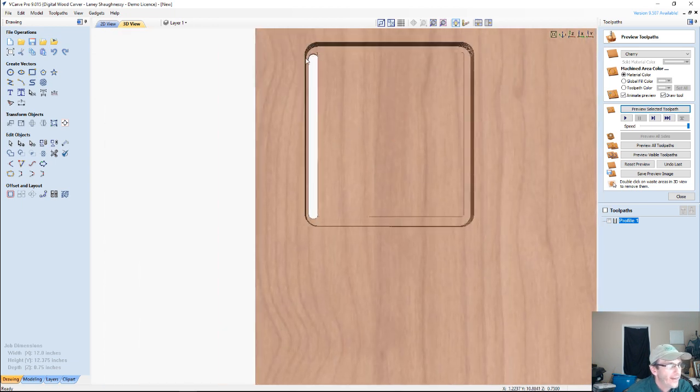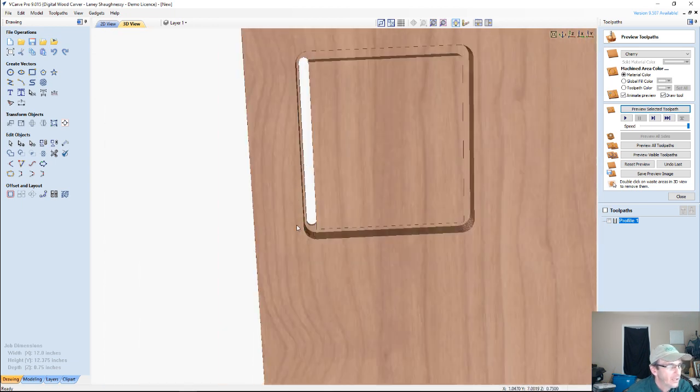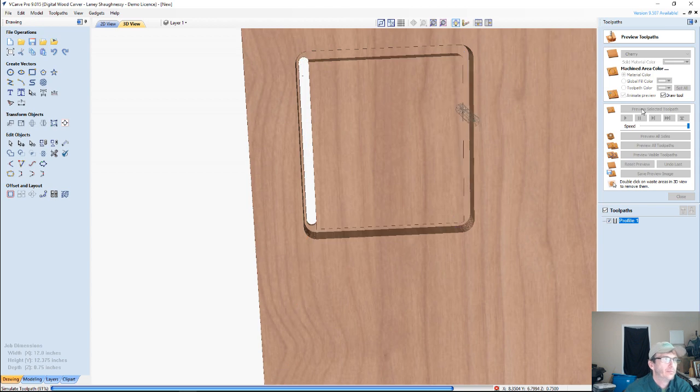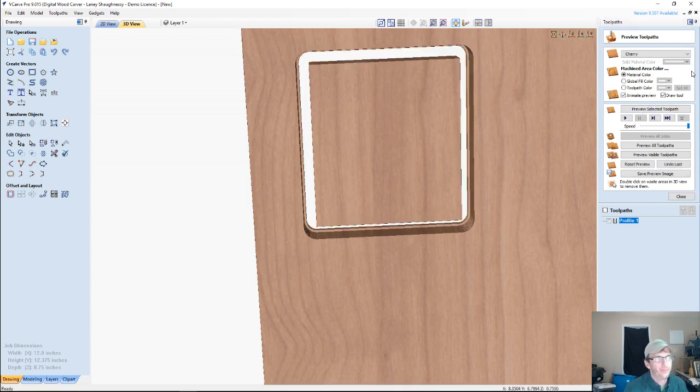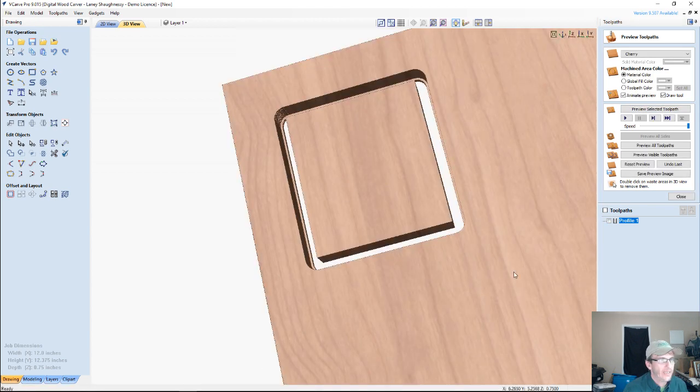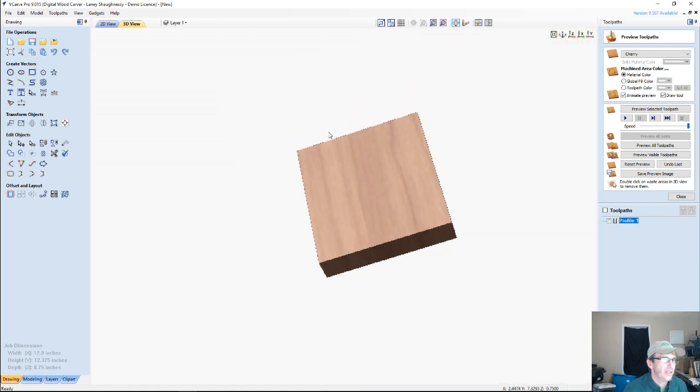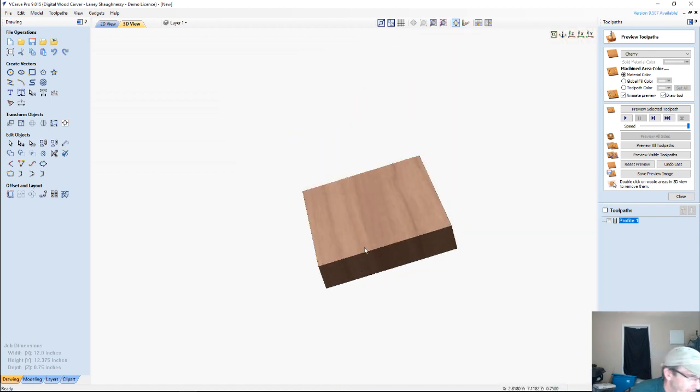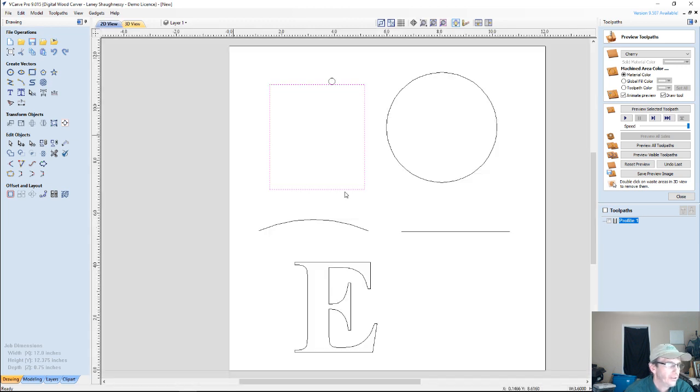So for those first 5 passes, it was cutting out away from the material, that 1/16 of an inch, and then on the last pass it's going to take the full plunge of the cut, the full 3/4 inch cut, and now it's going to come through and cut that part out. And what that does for us is it really keeps us with a nice clean edge, so we have to do less sanding. Well, let's take this a little bit further, and let's actually talk about our witness lines.